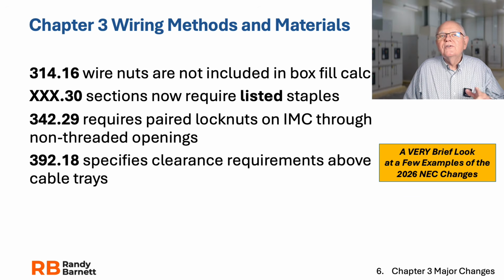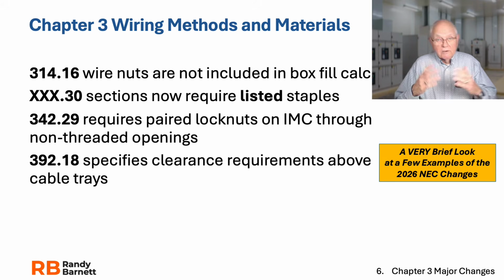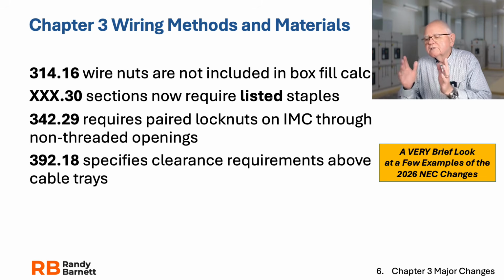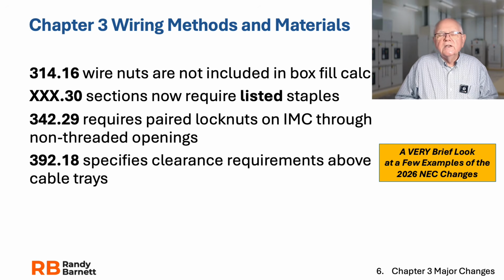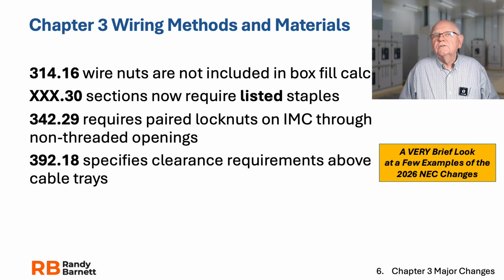Staples throughout these cables, so whether it's NM cable, MC cable, whatever it is you're using, if you're using staples, dot 30 was always, or it is, securing and supporting, right? And dot 30 says, to secure and support, you may use staples and listed the other means. Now it says our staples have to be listed. So you got to get listed staples to support that NM wiring, whatever it is you're doing.